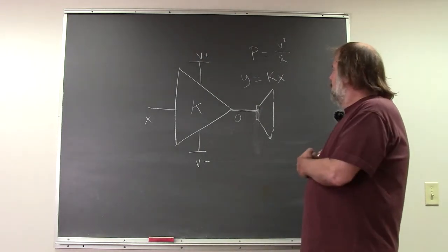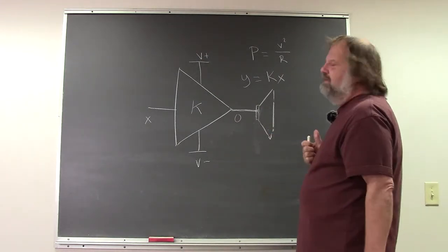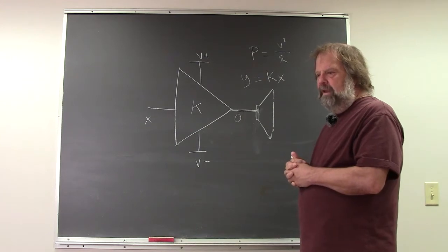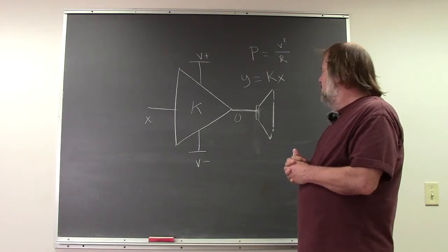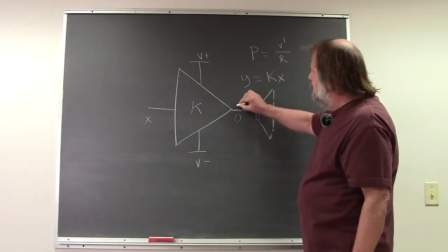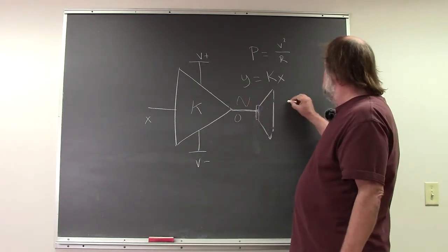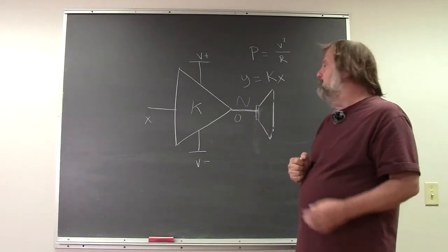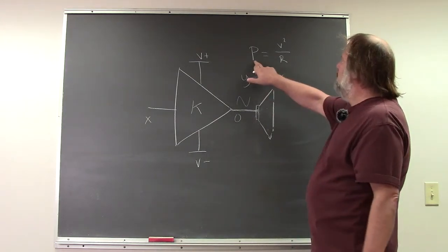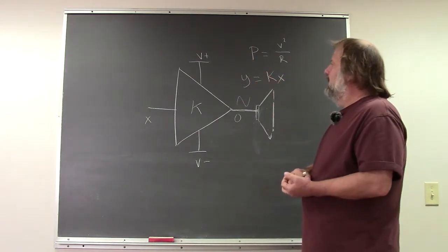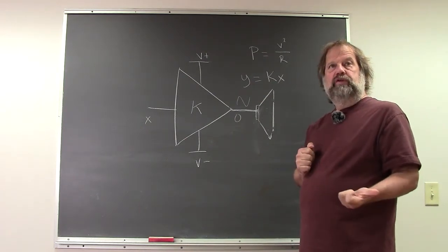Now, what does this mean? Well, the first thing you can take from this is that we want to put as much voltage into this as we can, because the more voltage we put in, the more sound pressure level comes out. And this is the first takeaway, because we talk about power amplifiers and power, but in fact we mostly care about voltage.